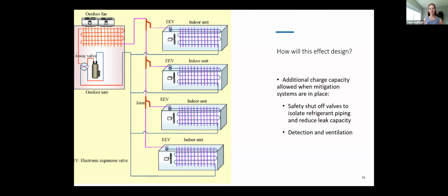So if you think about a VRF system, we essentially have a ton of refrigerant that is being circulated around your building to recover heat, to reject heat, to absorb heat. We are using all of this refrigerant to transfer heat from one space to another, and it can be a very efficient system. But that heat recovery is all happening through the refrigerant that is being cycled around the building. You then have these main lines that come back to your outdoor condensing unit.